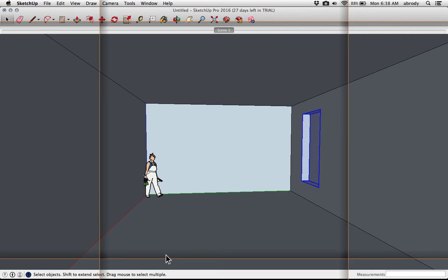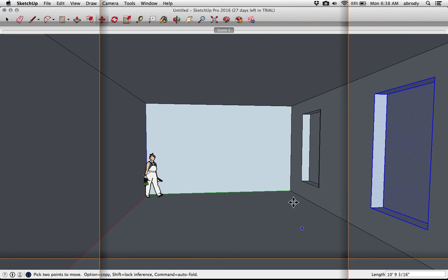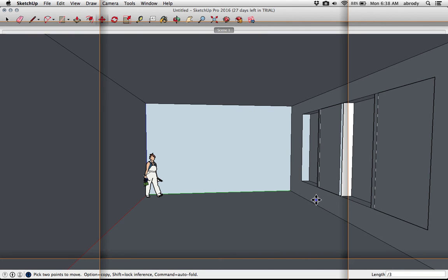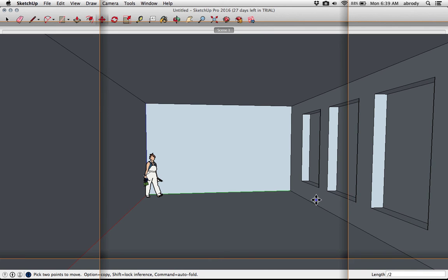So I'm going to make a copy of the window, and I don't know how many I want in between the original object and the copy. So I can use the slash modifier, and if I do /2, it will squeeze 2 copies in. If I do /3, that's too many, but it will try and squeeze them in. If I go back to /2, it will put them in there.